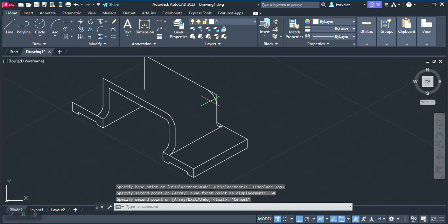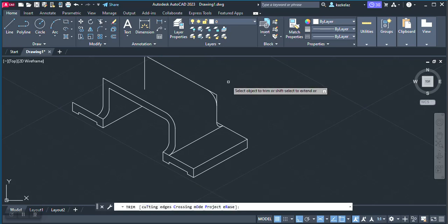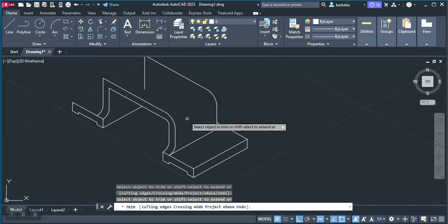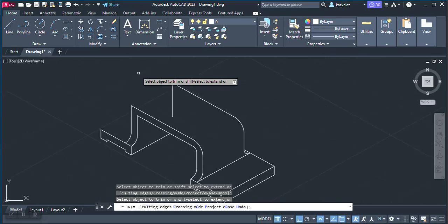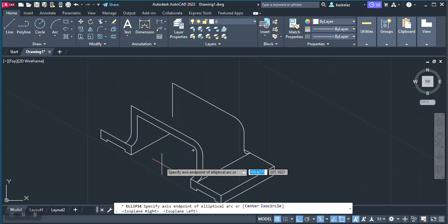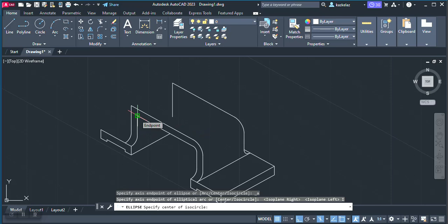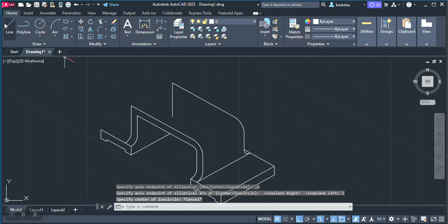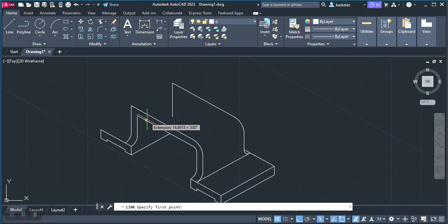So now what we need to do is also put those arcs there, right? So change your isoplane, change it to that. Select isocircle, and then from the center, we need it to be how much on that side. Okay, let's just first locate the arc on that side. So it's 6. Here I was supposed to move by 6 down, right? So it's 6.